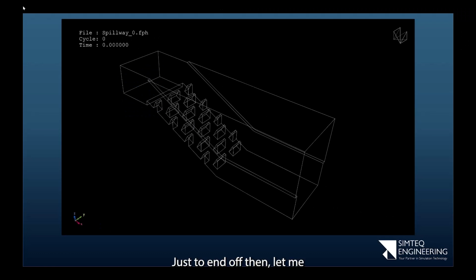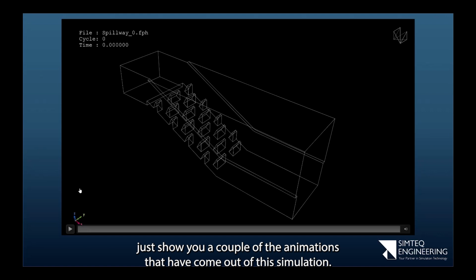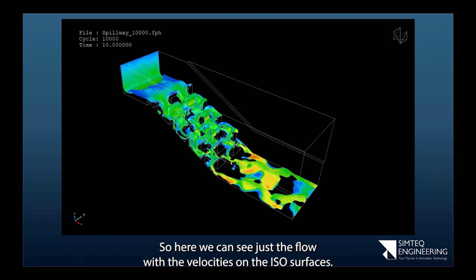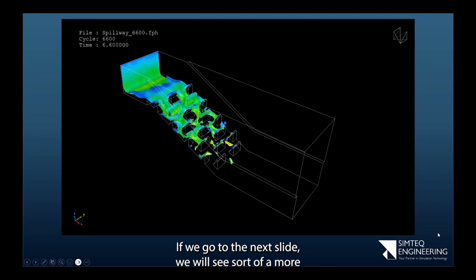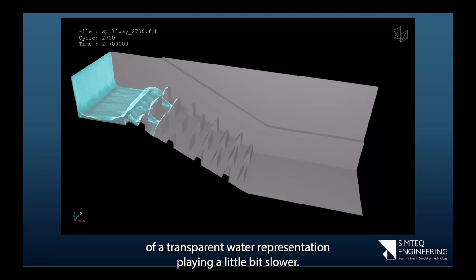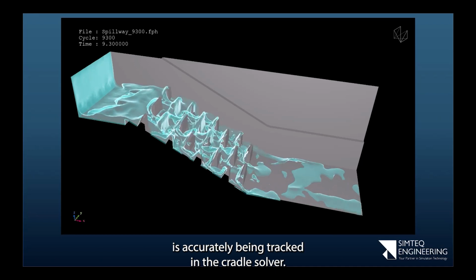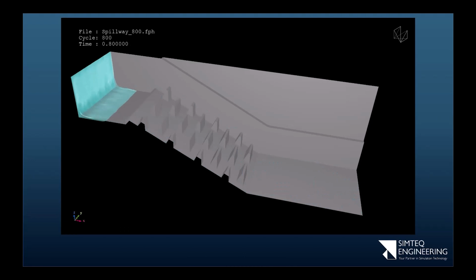Just to end off then, let me show you a couple of the animations that have come out of this simulation. So here we can see just the flow with the velocities on the ISO surfaces. If we go to the next slide, we will see a more transparent water representation playing a little bit slower. So you can actually see how the free surface is accurately being tracked in the Cradle solver. Let's play that again.